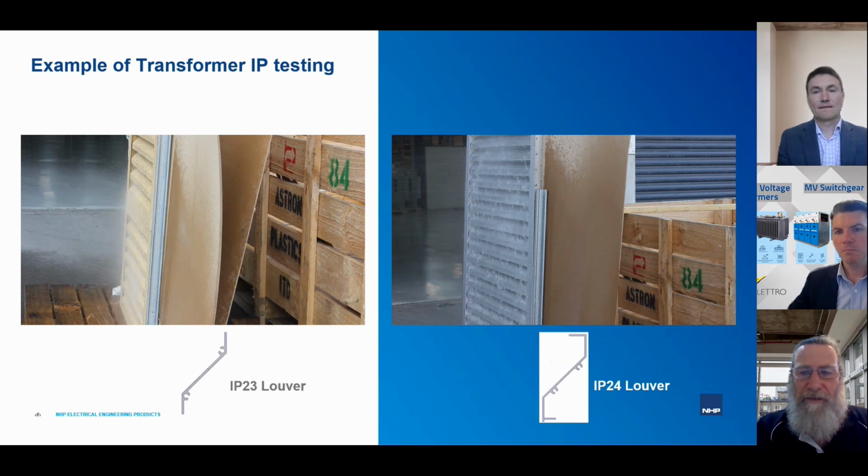Just to finish the story, in the end we had to get a design compensation from the customer to redesign the cover so that we put top hat ventilation on top to get the heat out of the enclosure. In this instance, we could get 100% rating out of the 2.5 MVA transformers.